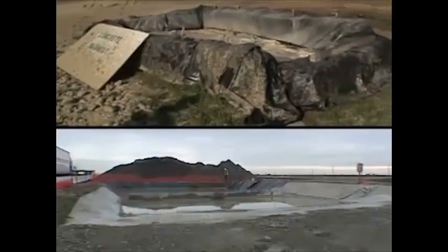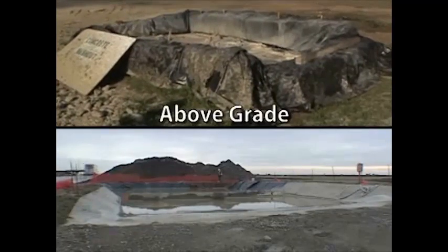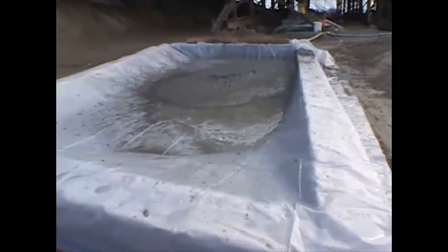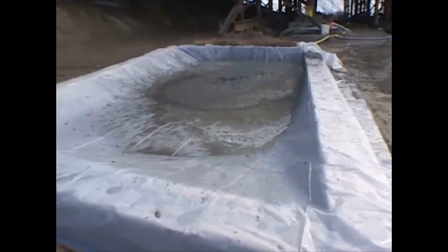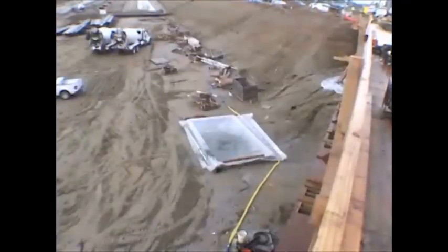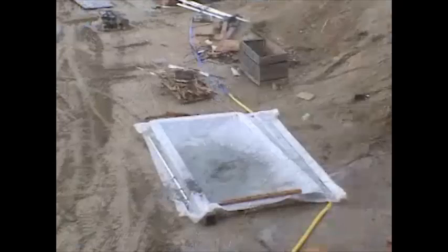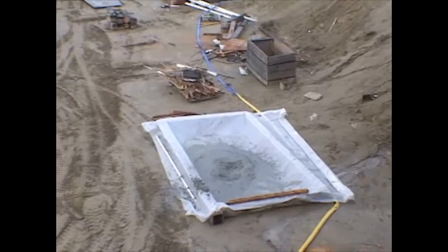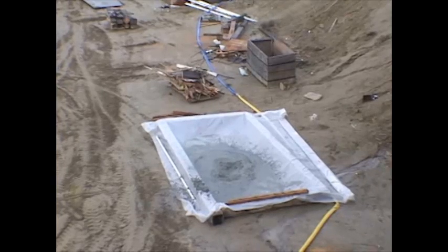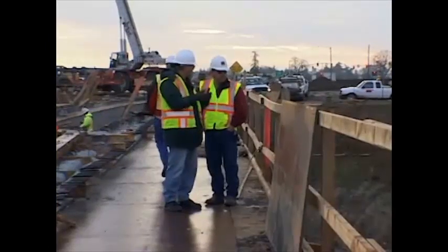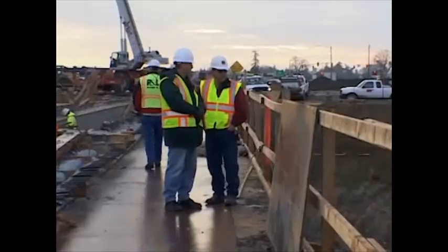There are 2 types of concrete washout facilities, above grade and below grade. Above grade facilities are constructed with a minimum length of 10 feet and a minimum width of 14 feet 9 inches. Basically, the concrete washout needs to be large enough to contain all liquid and concrete waste that is generated by washout operations for concrete wastes without seepage, spills, or overflow. Therefore, with approval from the resident engineer, the minimum length and the width of the facility can be increased.